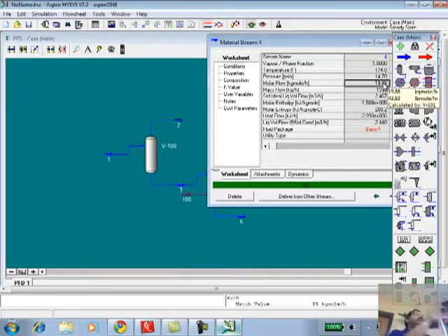It automatically puts it on no, so I accidentally hit no and it stopped. Oh yes, it would have found exactly 25. When I say exactly, there is a tolerance, a default value for the error. Within that error, it would have found the heat duty to produce 25 moles per hour.